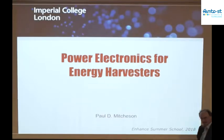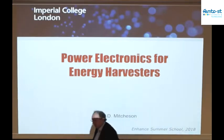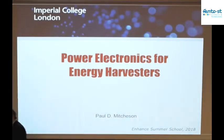Now, what I need to think about is how I design the power electronics in such a way that I can really maximize that total amount of energy through the power electronics itself, and also be able to control those parameters that I was talking about. I'm interested in power electronics typically in controlling the current in inductors and the voltage on capacitors. And so that can naturally reflect into the harvesting domain of controlling the voltage on the piezo capacitance, the voltage on the capacitors in a moving capacitor type harvester, or indeed, if it's an electromagnetic harvester, I can control the current in the inductance of the harvester.